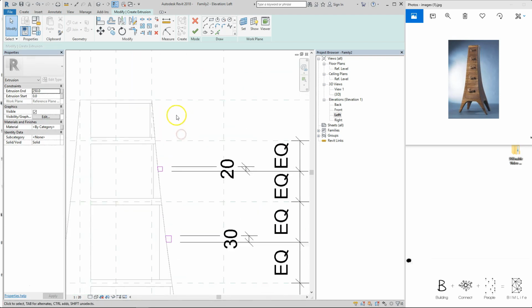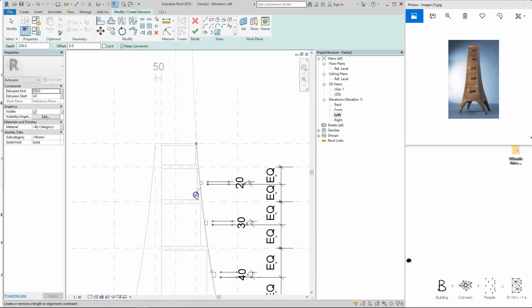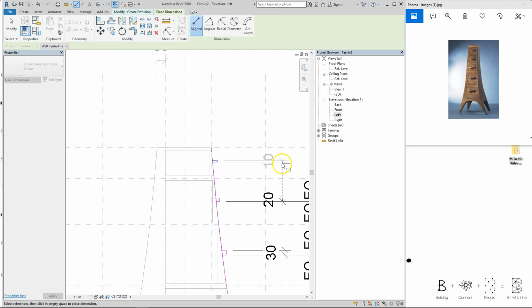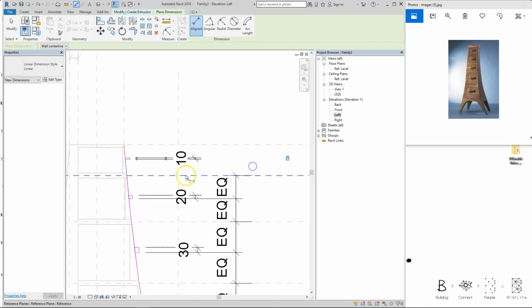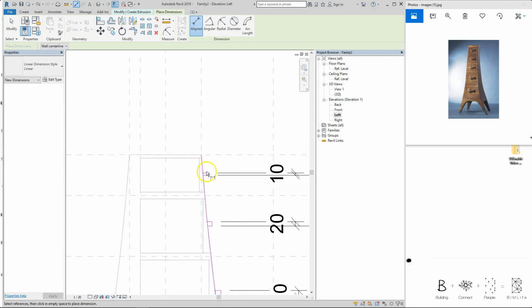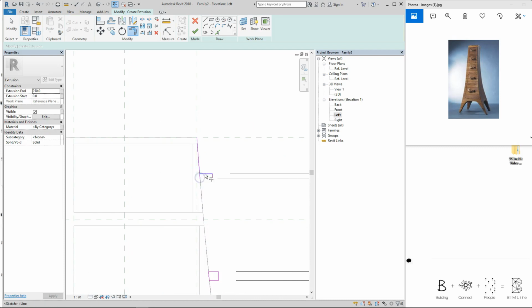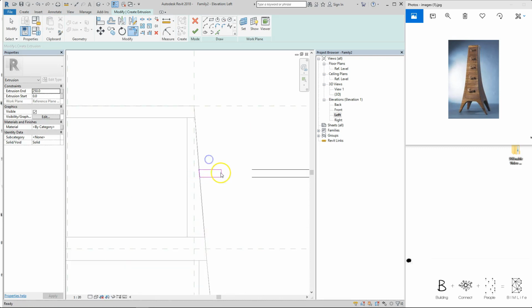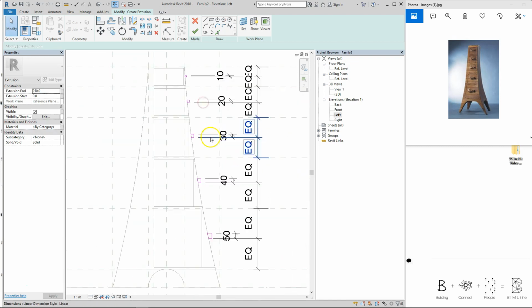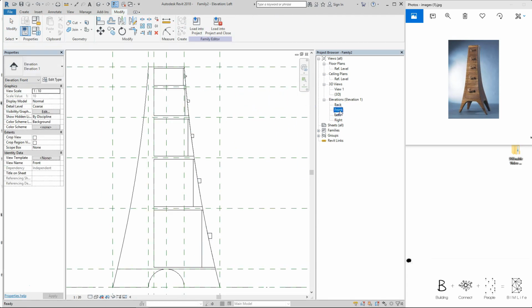Okay, the last drawer, pick lines, lock it. I'll just do 10 for the last drawer. Dimensions, lock it, equality sign, trim. Oops, trim this, make it shorter. Okay, that looks better. So having done this, press the green tick, go to the 3D view first.